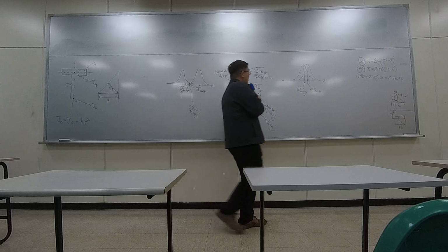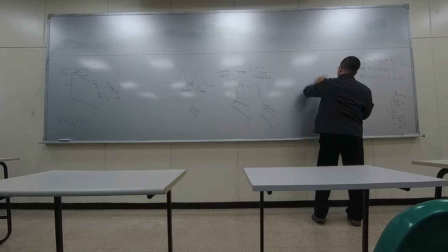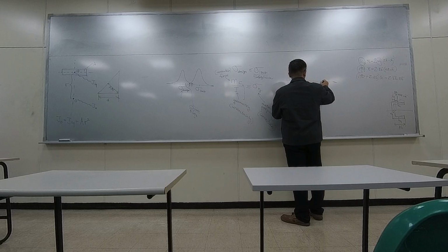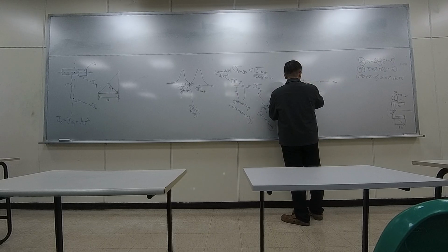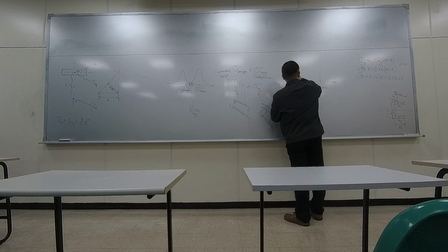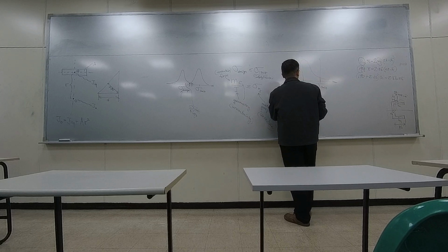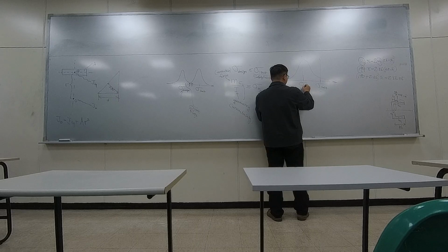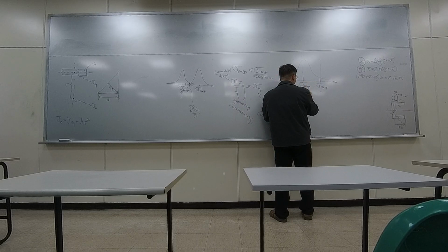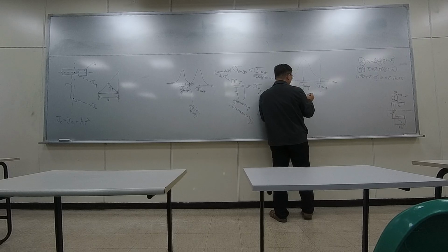So usually it's like this. In fact, if you have your design stress, and here's your limit, and here's your distribution, and let's say right now your design is on the limit, which equals the limit divided by the safety factor.